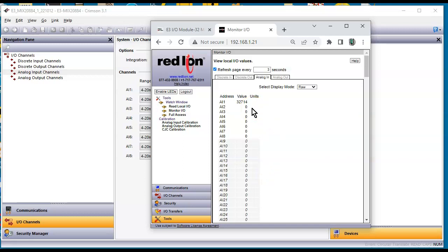All right, I'm still sitting at 20 milliamps, but this time, let me take it down to below 4 milliamps. So let me ramp this down. And on the simulator right now, we're sitting right there at 12.0 milliamps. So that's the halfway point between 0 and 32,000 there, if you will. Let's take this all the way down to 4 milliamps. Oops, pressing the wrong way here. Hold on, team.